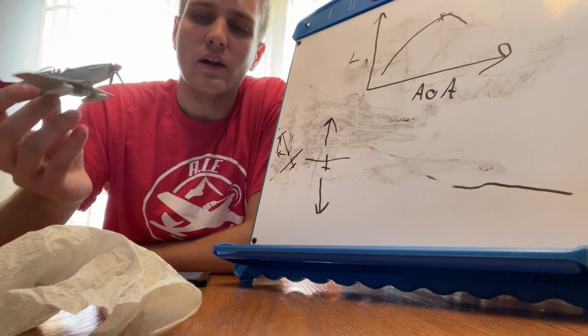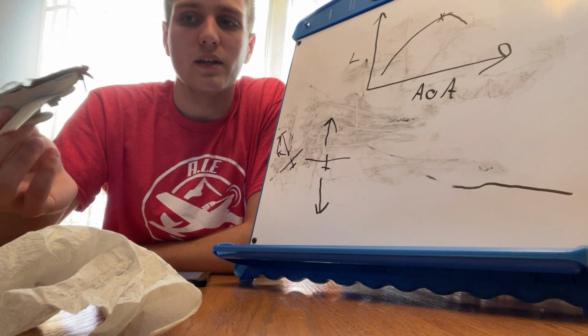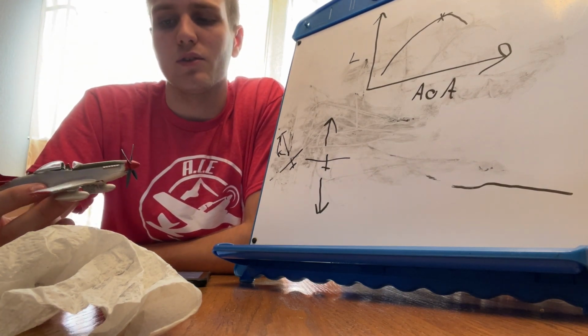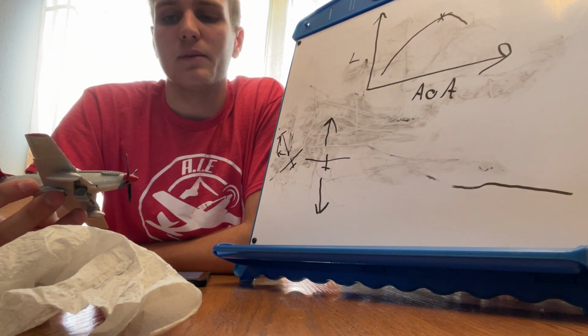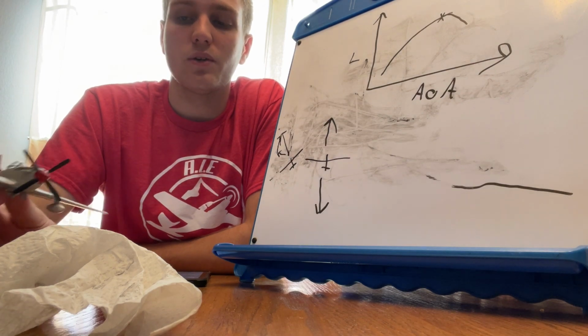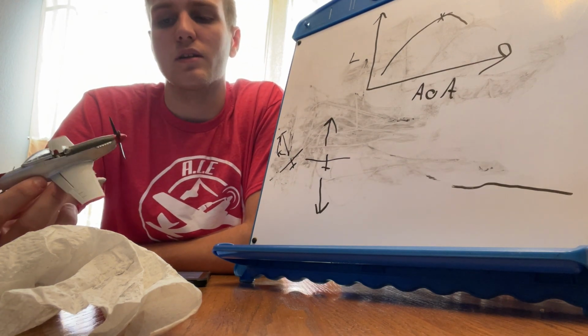So in our airplanes, I believe 3.8 G is our max load factor we're allowed to use. And that's basically saying anything greater than 3.8 G's, you're risking breaking the airplane.